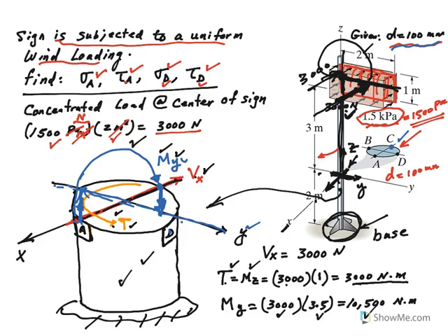Let me erase some of this stuff here. It's getting too messy. All right, so let's look at this. Remember, there is a torque. This torque creates the same shear stress. Remember, shear stress is maximum on the outside. So this is the TC over J here, and the same TC over J, look at the direction. It's going like this, right? So TC over J here.